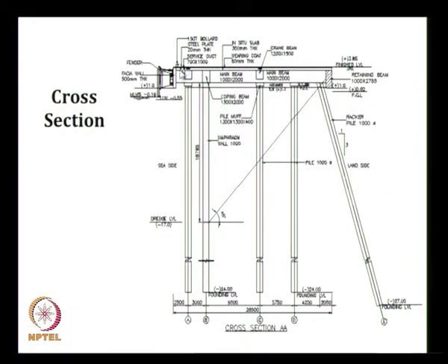All these are required to be placed here, and we have a bollard here which is to be fixed. So typically we need about 2.5 meter from the center line or clear 2 meter to make these utilities as well as the fixing of the bollard. So this is a requirement, and this is a fender which is called a conical fender, a frontal board, so that it varies from mean low water spring and slightly above the highest high water level.